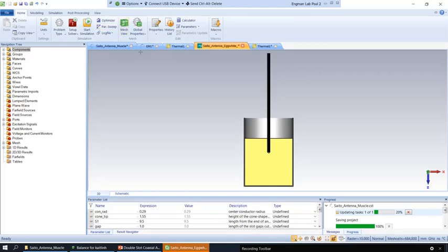And then the last thing I want to bring up is, up to this point, we have discussed doing a coupled simulation. And by that, I mean we have these sub-projects, an electromagnetics project and a thermal project. All of the stuff that I've described here, optimizing and parameter sweeps, remember we're optimizing the S parameters, which is an electromagnetic result. It is in this EM1 subfolder, which is a CST Microwave Studio project. So for all of this parameter sweep stuff, you don't need to do the update task coupled simulation thing that we've been doing up to this point. You can just run the simulations directly in this folder.